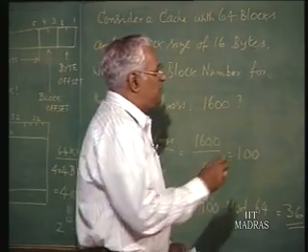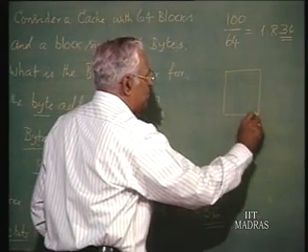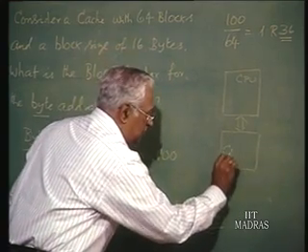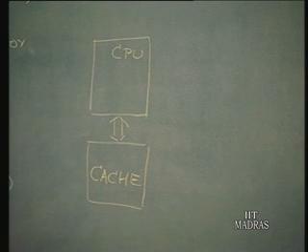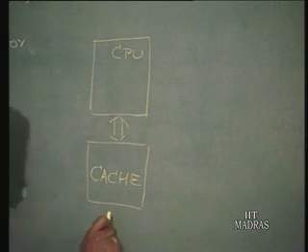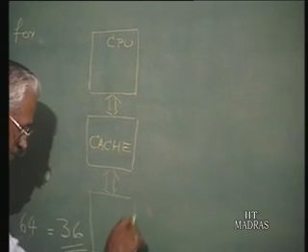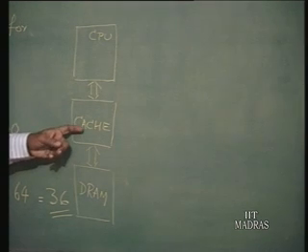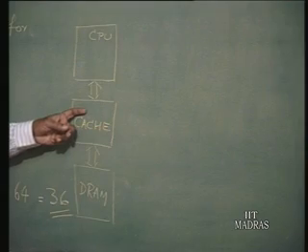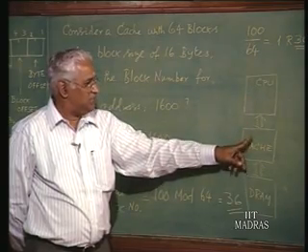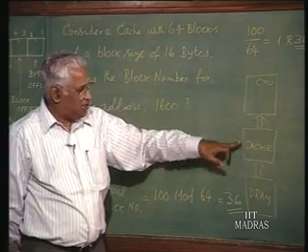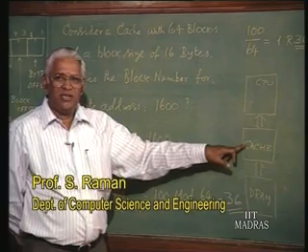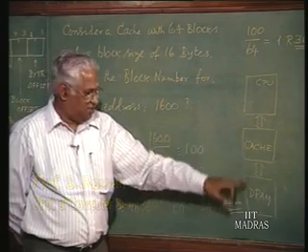Now, for this you must know that we have the CPU. The CPU accesses the cache, and we had said earlier, if the cache does not contain what the CPU wants, that will be accessed from the DRAM memory, right. Now, you see the problem. CPU wants to read something from the cache. If the cache does not contain it, it will be got from the DRAM. Once the CPU has got it in the cache, it can read, that is not a problem. Then the contents that the CPU reads from the cache and the contents in DRAM will be the same. Suppose the CPU writes into that location in cache, then the cache contents and the DRAM contents will be different.